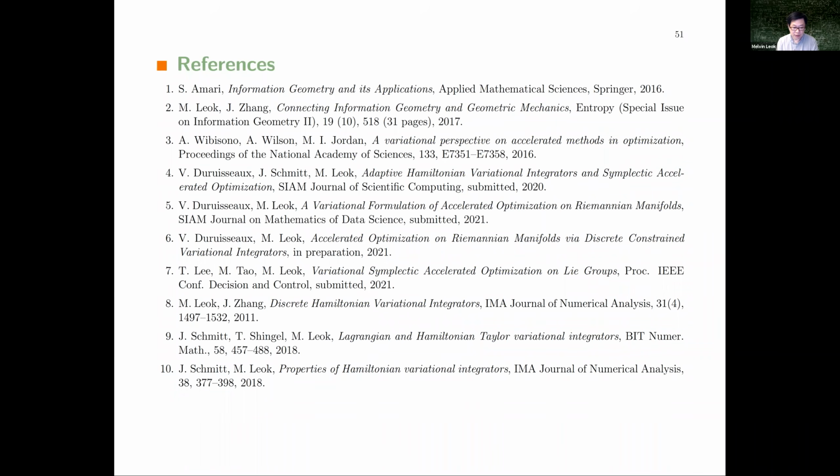Okay, so let me say a little bit about this optimal rate of convergence thing, which is the following. If you have a problem which has multiple time scales, then one interesting way, which we're studying now, to construct good methods that allow you to take larger time steps than the fast dynamics is to build the fast dynamics into the spaces you work with. So if you have something with fast and slow dynamics, and the fast dynamics is oscillatory but well approximated by, say, sines and cosines, then you might consider using shape functions which have sines and cosines in them instead of just polynomials.